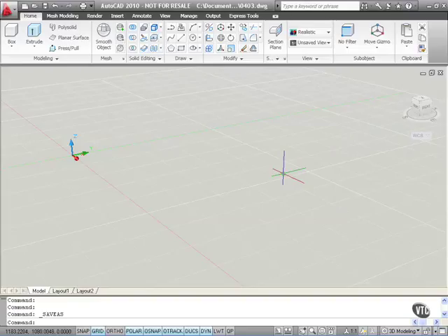Mobile phone companies tend to use stereolithography to create prototypes in plastic and polymers of their mobile phone casings. They can then perform destructive testing on them rather than use an actual phone case, which obviously costs a lot more. I'm in the 3D modeling workspace here.